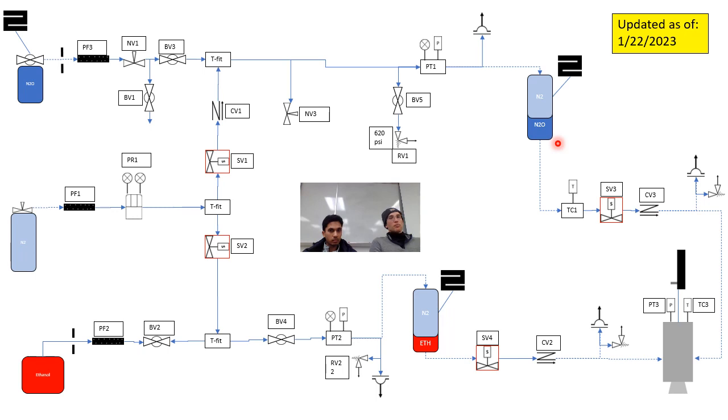So the reason for that is we want to run our test at as low as possible, 600 psi. That's kind of what we've given ourselves as our number, because it gives us a safe buffer of about 10 degrees Celsius above the 450 psi minimum at 0 degrees C. So even if it goes from 0 degrees C to 10 degrees C during the test, because ice melts or because it just heats up in the lines, as long as it's at 600, we're still safely a liquid.